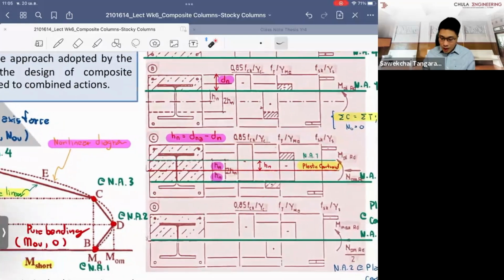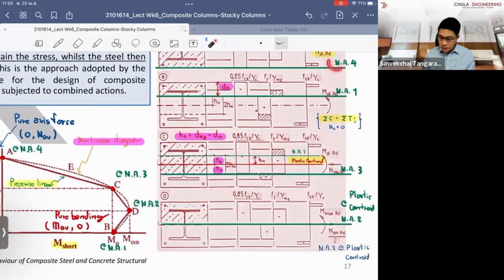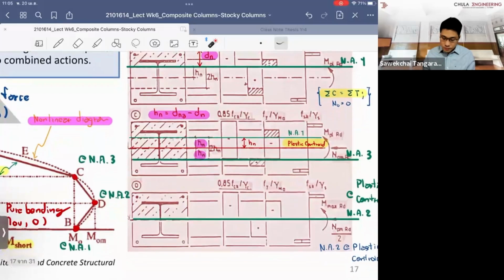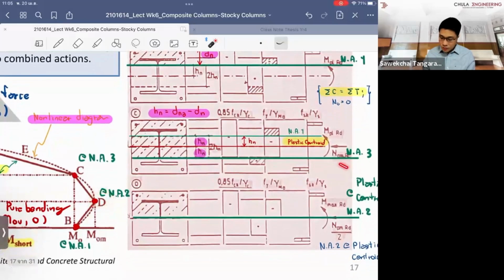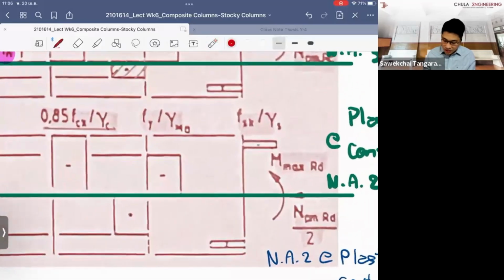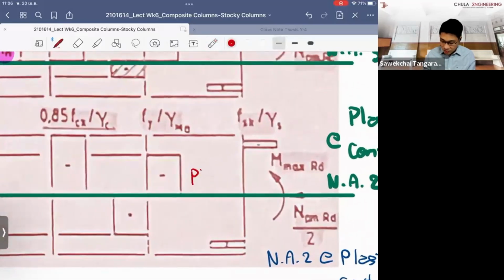The point C you can have is when you raise the neutral axis depth from the bottom surface to where you have the level of the plastic neutral axis depth just sitting below the plastic centroid with the value of Hn. The point D, you just raise the location of the plastic neutral axis depth to be at the level of the plastic centroid, right? This is also the level of the plastic centroid as well.